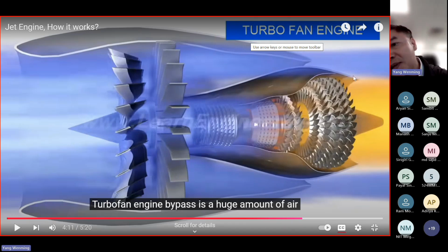Then the last part is a nozzle. In this design, in this part, the diameter is the biggest one, and from this position to the exit, we can see the diameter will decrease. So by this design, we can create a nozzle shape. We know the function of a nozzle is to increase the flow speed, correct? In this process, it converts the thermal energy into kinetic energy and increases velocity, thereby we can produce a greater thrust for the aeroplane application, correct?